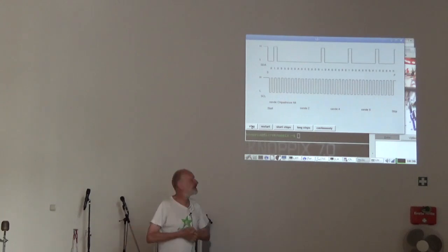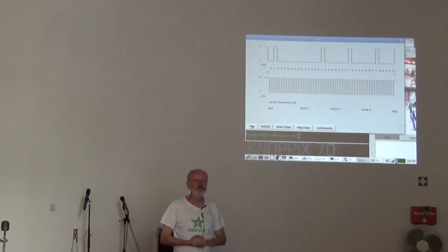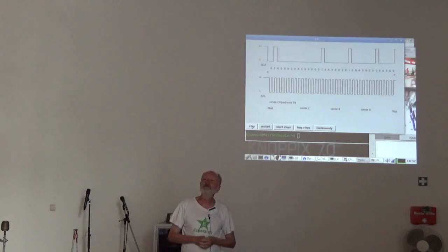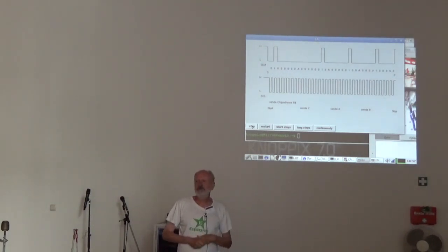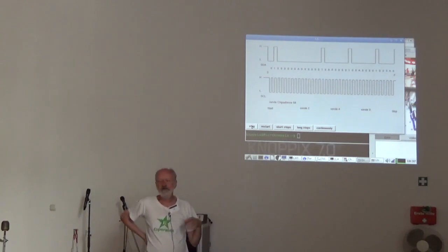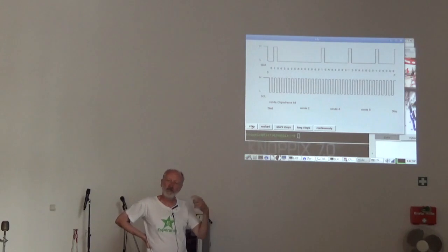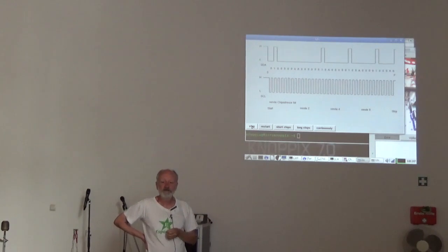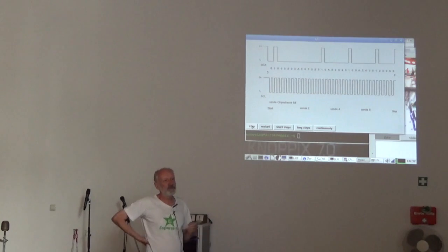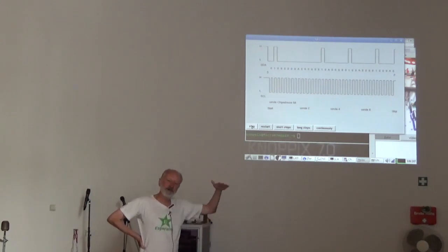This is so because the LEDs must have a current of several milliamperes, but the I/O expander that I use has only a weak high-level driver capability, a very weak driver capability when it is high.